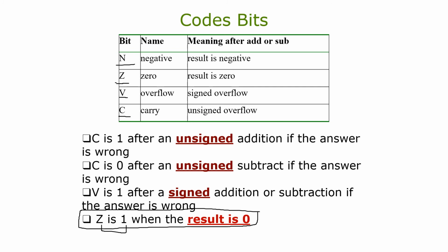There is one bit that has not been described, that is the N bit. This is 1 whenever the result is negative. If at any point we need to use that negative bit, then I will describe its role in more detail. But for now, we're going to use the description of the Z bit and write an assembly language program that conditionally executes some instructions.